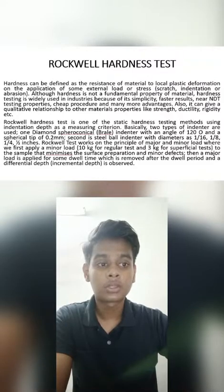The Rockwell test works on the principle of major and minor load, where we first apply a minor load, 10 kg for the regular test and 3 kg for the superficial test, to the sample, which minimizes the effect of surface preparation and minor defects. Then a major load is applied for some dwell time, which is removed after the dwell period, and a differential depth is observed.